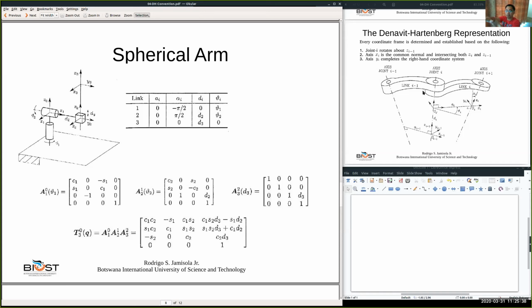So in this case, if a pan tilt joint draws the shell of a sphere, depending on how much the tilt can do, it can draw a hemisphere. Okay, the hemisphere like that. It can reach the shell of the hemisphere with a radius equivalent to the radius of the arm of this tilt arm. Okay, that's a pan tilt joint.